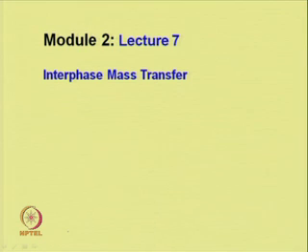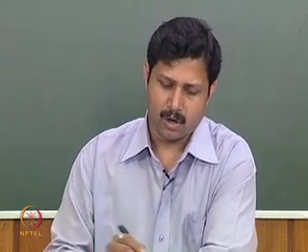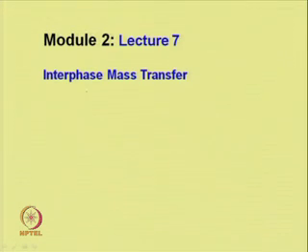Welcome to the 7th lecture of module 2. Module 2 is on mass transfer coefficients. In this lecture we will continue our previous lecture, which is interphase mass transfer. In the previous lecture we have seen that to calculate the flux for interphase mass transfer, we need to know the interfacial concentrations, but the interfacial concentration is not easy to measure by a simple device, or we can say the interfacial concentration is not measurable by a simple device.